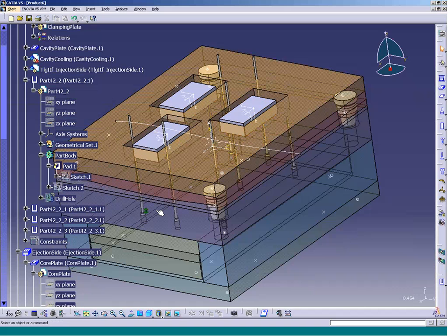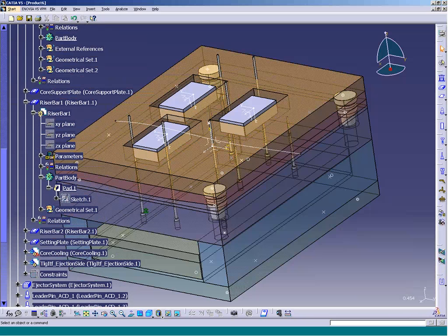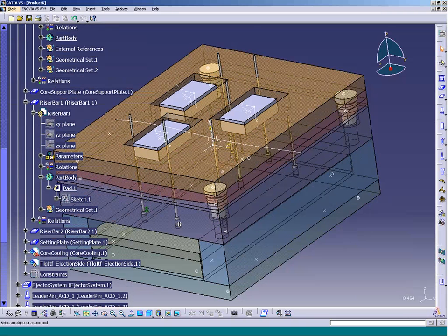What I found is there's a lot of stuff inside of mold tooling that I've actually started using inside assembly design. It's not so much for tooling, but when I want to drop in bolts, like a product with bolts and washers and everything else, all I want to do is pick a spot, and I want the hole to be there automatically for me. So all I'm doing is defining points and picking the points, and especially if the points are within a sketch, not only does it drop in the holes, I don't have to use a reuse pattern with it. It drops in all the components with it, and along with it, it gives me access to those technological results, which I can then use within the manufacturing process. So I'm actually starting to use this stuff outside of the tooling industry as well.